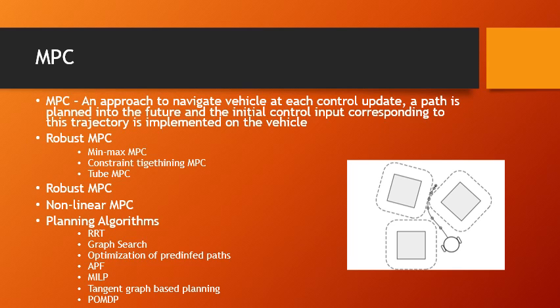In Tube MPC, it uses an independent reference model of the system to ensure the actual state converges to the nominal state. It does not take advantage of favorable disturbances, hence the benefits of navigation on a linear model are used, making it usable for robust linear and nonlinear problems. Nonlinear MPC approaches to MPC-based navigation rely on a nonlinear kinematics model. A nonlinear trajectory tracking system can be used to ensure the actual state converges to the nominal state. In scenarios focusing more on control, MPC yields positive results and guarantees that safety is easier with kinematic models.